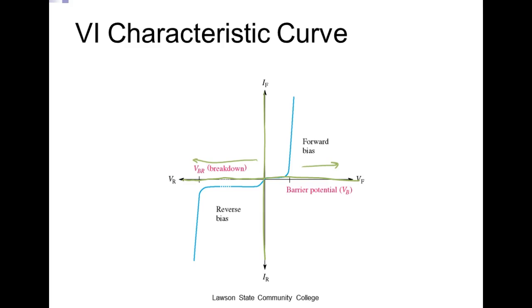Now normally a rectifier diode, we want to operate somewhere in between here, right? On a regular rectifier diode, we never, ever want it to break over. If it breaks over, we're going to push current through it. It's dropping a voltage, it's going to produce a lot of power real fast, and it's going to burn up. So rectifier diodes and small signal diodes, we never want to exceed the breakover level. We did it on purpose, but we protected that with a 10 megaohm resistor, right? So we broke it over on purpose.